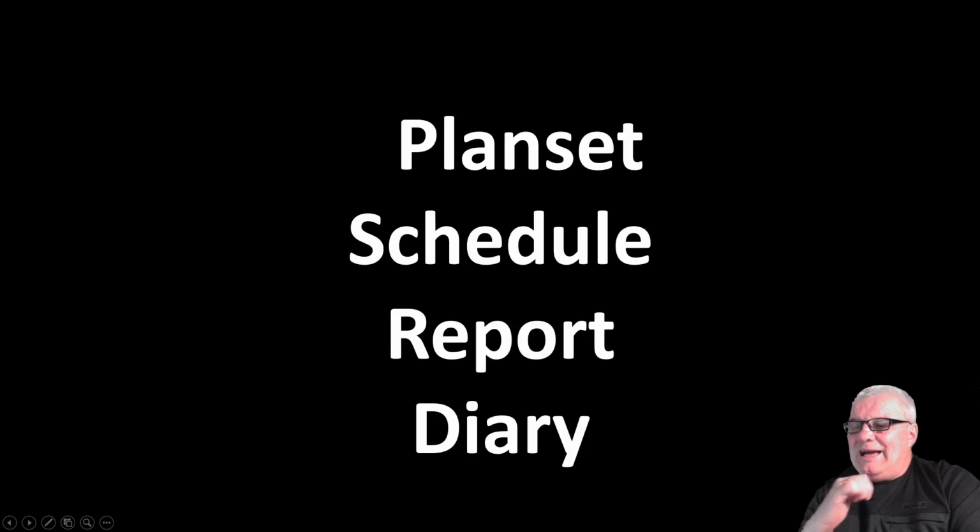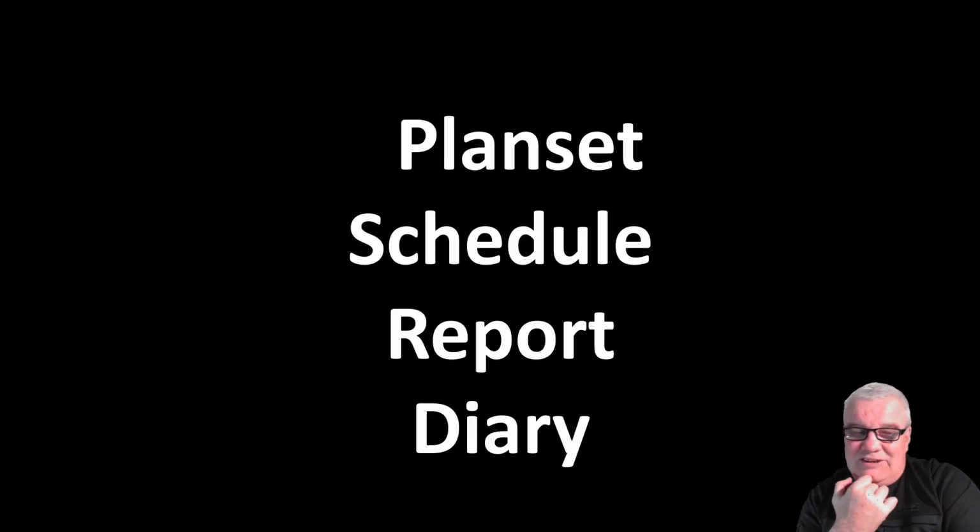And then the final part of the project is getting the evidence together and putting that together. So you're going to have a plan set, which is a set of plans, a schedule of quantities. So this is how much of everything, how much pipe, how much curb, how much road surface, topsoil stripping, earthworks moving, off-site, on-site, all of these things. And that will all be put together, and then you'll have to cost that schedule. You'll cost it out, and we'll provide you with some figures and stuff on that. And that will all be put together into a report together with your diary.